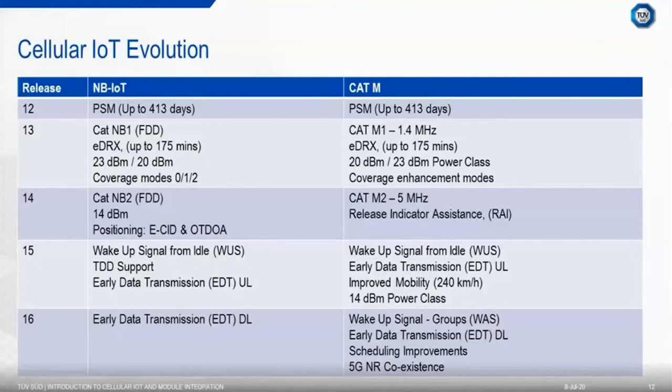So many improvements to narrowband IoT and Cat-M technology have been made since their inception. As with all cellular technology, there is a constant evolution and refinement to improve the operation. Most of the added features focus on battery-saving features, first introduced at Release 12, and power saving mode gives the greatest benefit, but other features have been implemented that, whilst quite small in isolation, provide a marked power usage saving over a required life of 10 years. An example of this is a new power class reducing the transmitted power to 14 dBm.